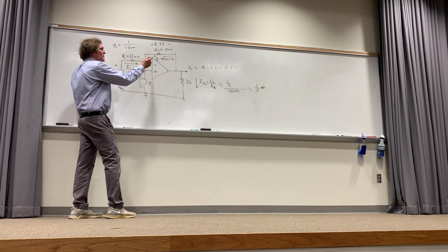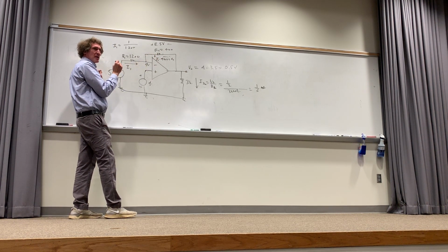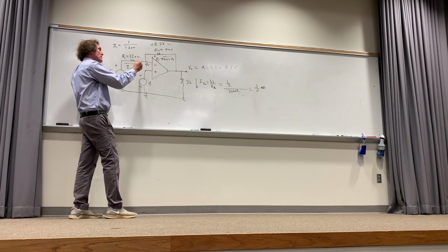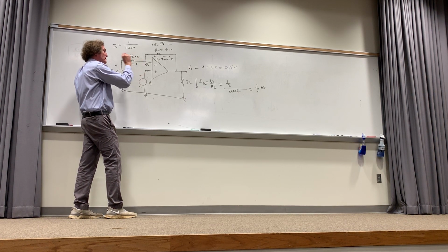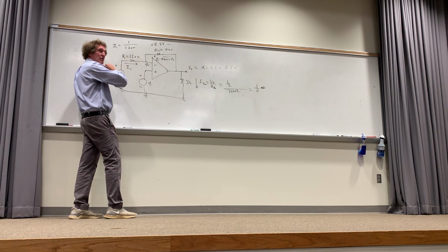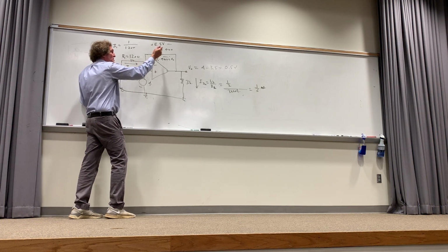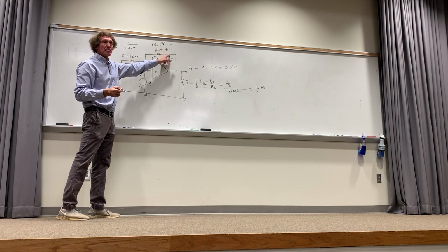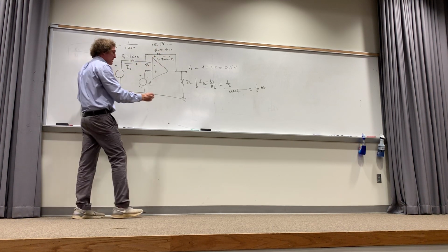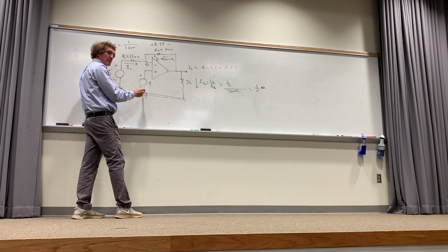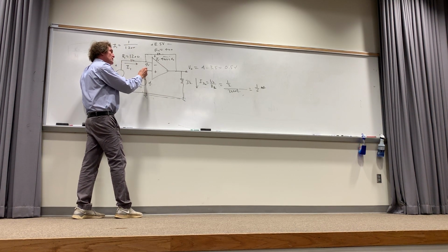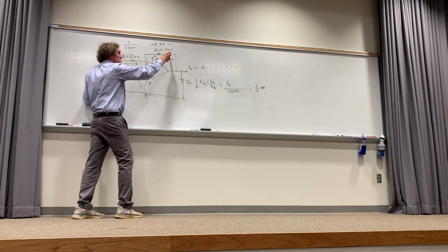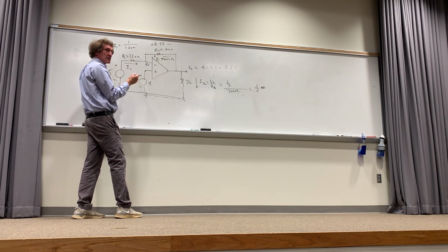They might have just asked for the voltage across R2. That might be what they get. V out itself will be this. If I know that current I1 is 1 over 1200, right? 1 over 1200 times R2, or 3.5, is the voltage from here to here, right? Correct? Now, if I want to find the output voltage, I have to start here, right? I get an increase of 4, and then I get a decrease. Take a look at the signs, right? Decrease of 3.5. That leaves me with 0.5 volts.